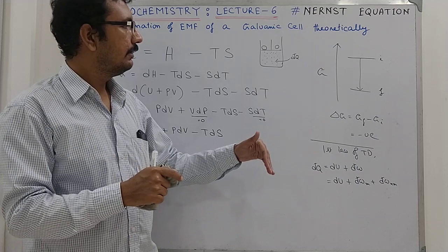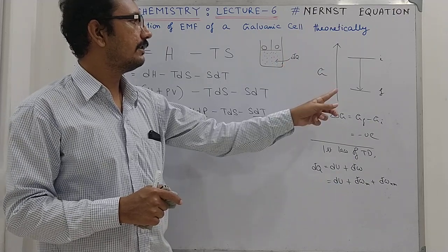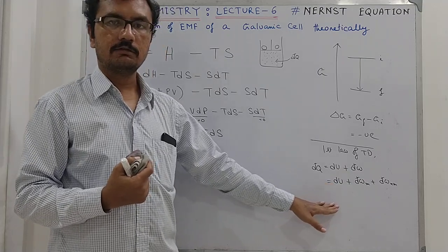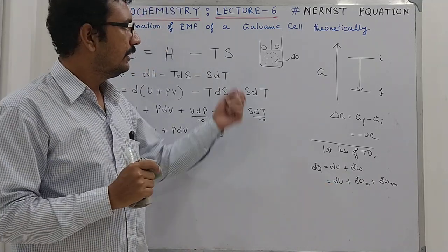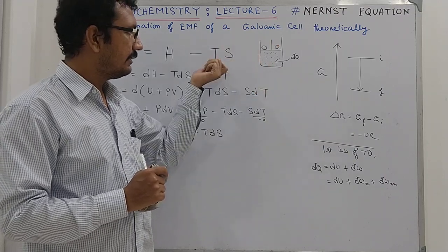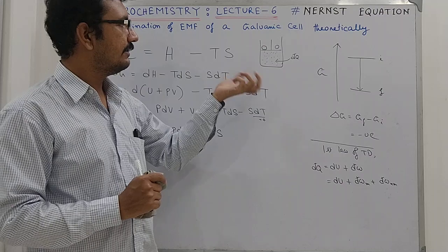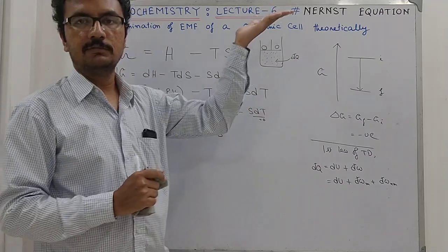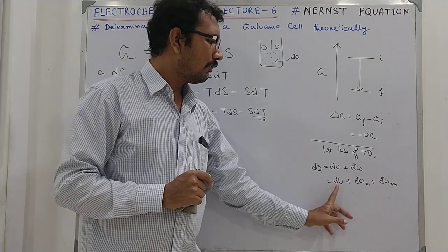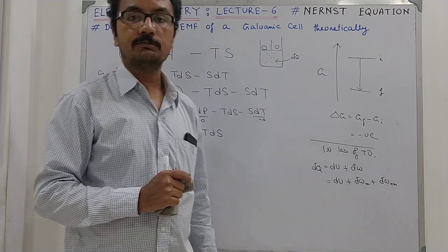And there is no property of a system like work. It is not that the system has this amount of work in the final state and this amount of work in the initial state, so subtract it and you will get the difference. That must not be the procedure. You have to collect the information throughout the change. For this step, you get this amount of work, you take it. For the next step, you get that amount of work, take it, write it, and just add them up. When you add all these, you will get this value. So the modes of getting the values are generically different, but you are writing them in the same form.